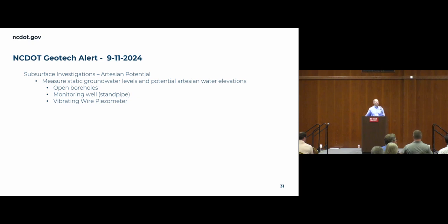So this, in addition to a few other projects that Geotech and the divisions are working towards, led to a memo, or a kind of a blast, from Geotech. You probably saw it on September 11th. That didn't sound good. They sent out an email on September 11th, basically talking about the artesian potential. So basically reminding people, amongst a few other things, to measure static groundwater levels at potential artesian water elevation. That could be open boreholes, monitoring wells like a standpipe, or a vibrating wire piezometer.